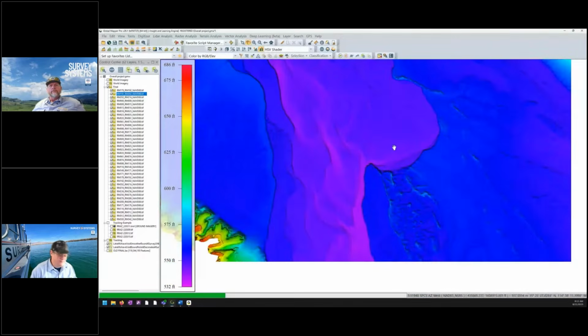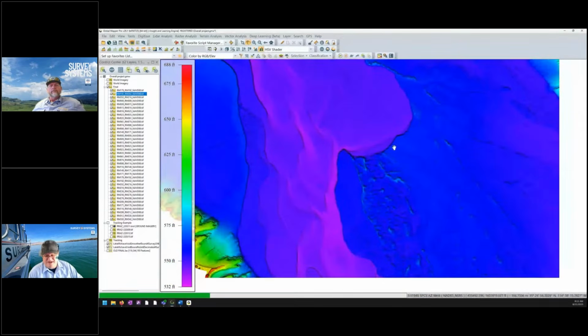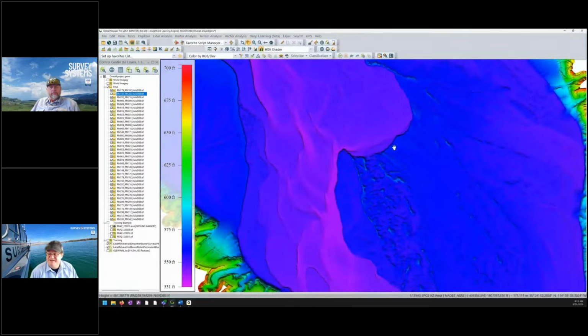And yeah, when I'm doing the field tracking, I'm exporting out the TIFFs of each day, and each one of the TIFFs I would export as a GeoTIFF. That makes it a much smaller file that I can then email over to the field crew, and the field crew can bring that in as Matt's out there on the boat. He can load that TIFF in and have it in the background and be able to see exactly where he was the day before.